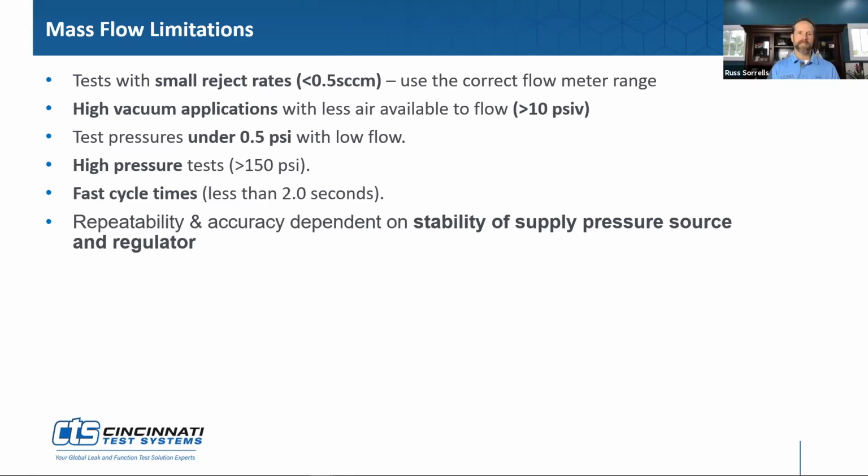And suck the guts out of your flow meter. Yeah. And also, if you're in the low pressure ranges, 0.5 psi and lower, there's not a whole lot of flow associated with that either. And if you're testing in high pressure, getting above 150 psi tends to be a challenge because there aren't that many flow meters on the market that test in that range.